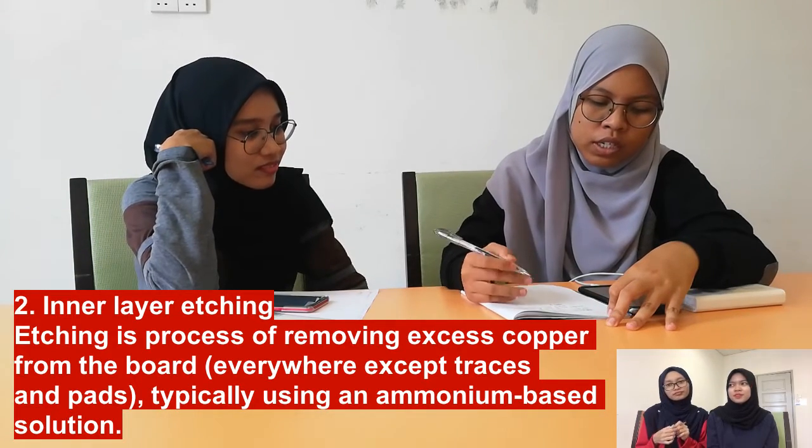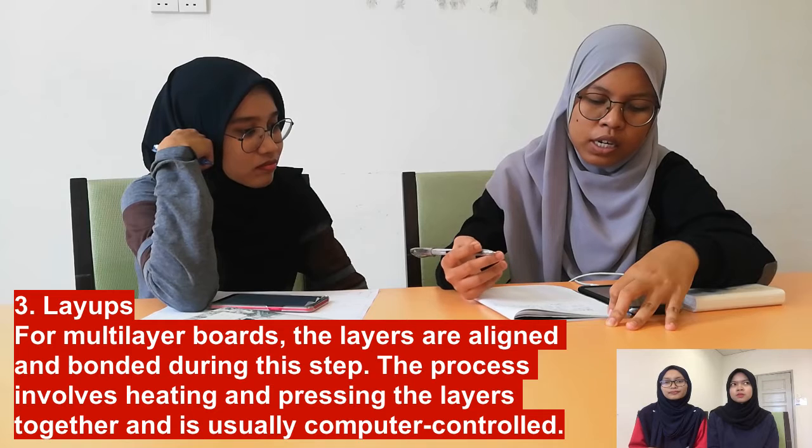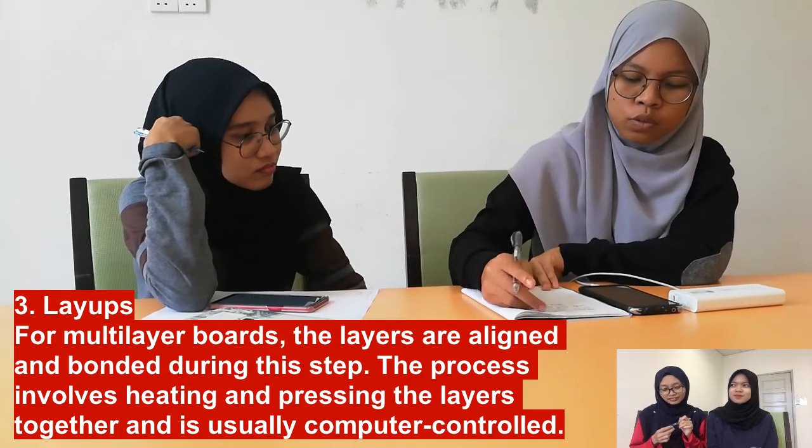The third step is layup. Layup is mostly used for the multi-layer boards, in which the layers are aligned and bonded during this step. The process involves heating and pressing the layers together and is usually computer controlled.